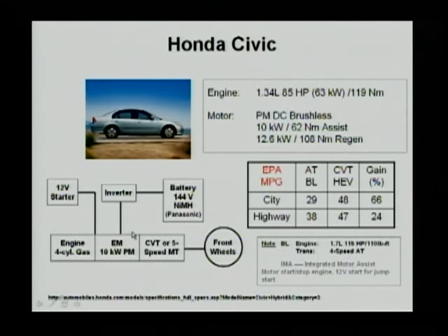And the motor is powered by an inverter, and the inverter takes power from a nickel metal hydride battery, at 144 volts. So this is also called a common shaft design, and it is a torque coupling. It is a parallel hybrid. Even though position-wise it looks like a series from engine to motor to vehicle, energy flow wise it is a parallel hybrid. And you can see that in this system design, even though the newer model has a 15 kilowatt motor,